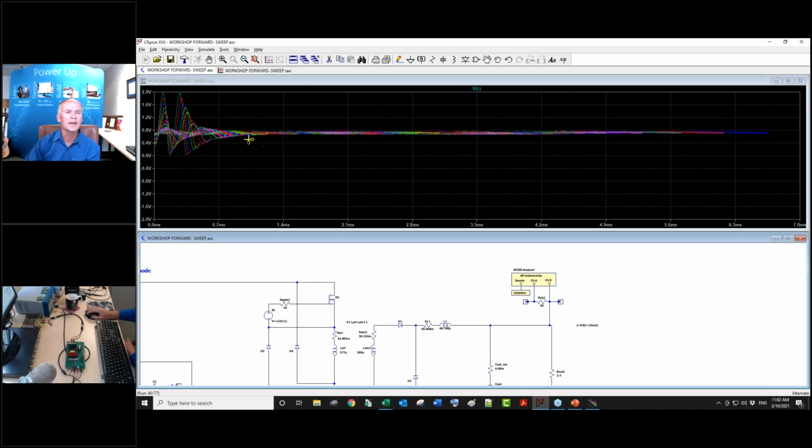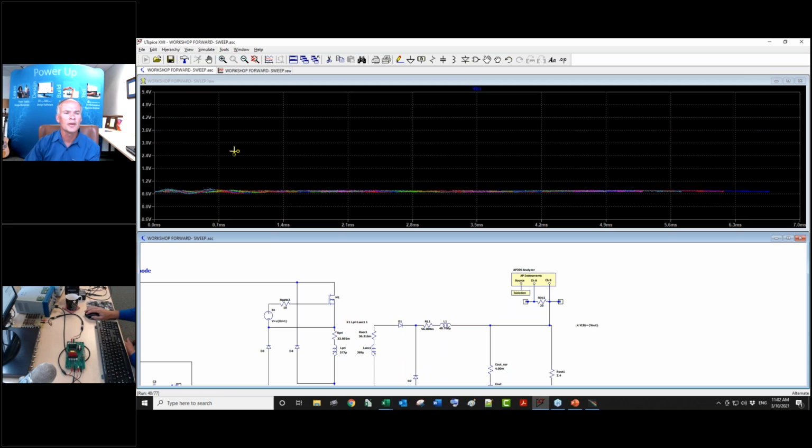So now we see how this error amplifier signal is growing on each sweep. Okay, 2.4, and we're going to see something interesting happen in a minute. Quite a big change on each sweep here. And I see what happened there. It went all the way down to 0 volts. So my error amplifier is now railing out at the bottom end. Okay, so I'm overdriving the system.